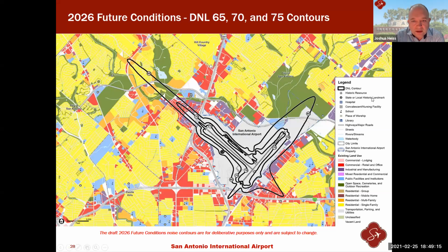And taking a look at these maps in the Blanco corridor along here, what we provide to the community is awareness of where noise is generated from aircraft operations with these contours, so that planners are aware of where noise is in the community, and most importantly, where it will be going into the future, with our dates identifying future conditions into 2026.